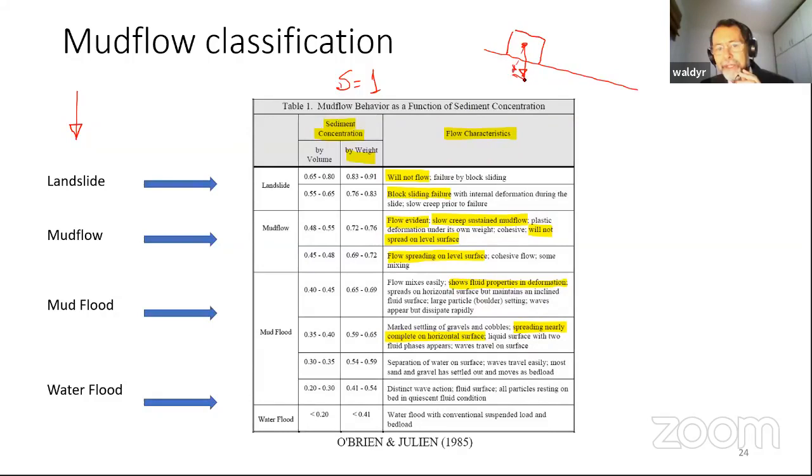One is normal, the other is tangential. This tangential component is the driving force for the block to slide, not to flow. And then you have friction that's going to be mobilized in order to prevent this. Depending on the inclination, you may have the slide, not really the flow in the material. We don't say flow in the material.